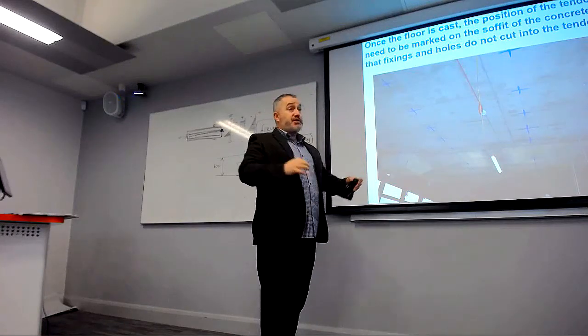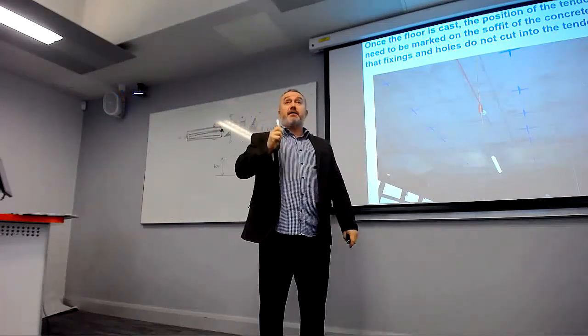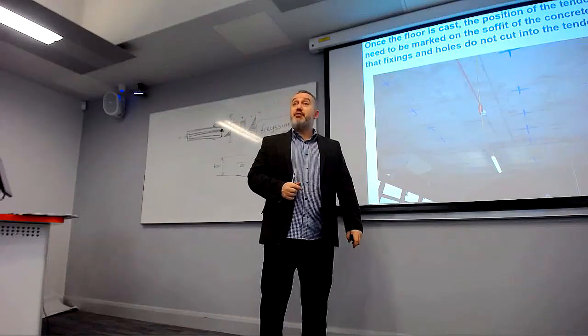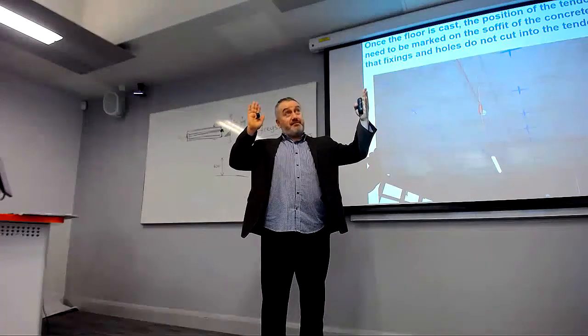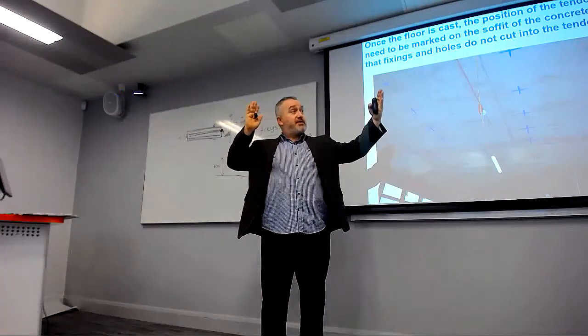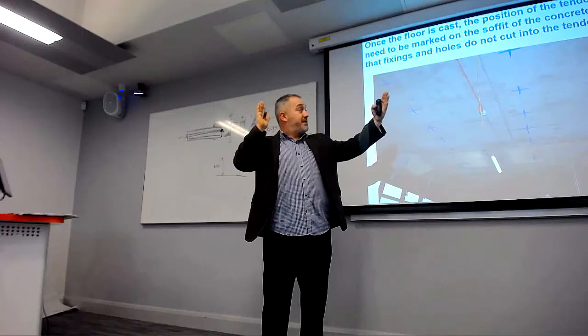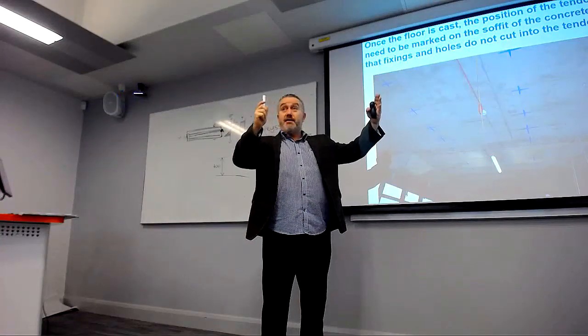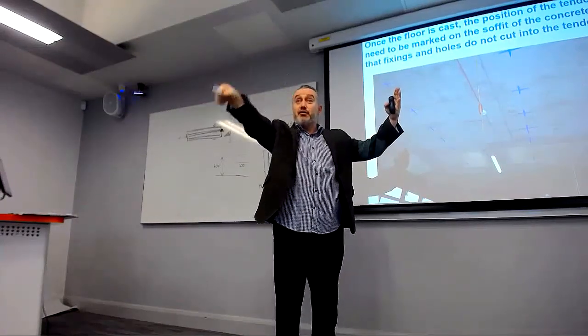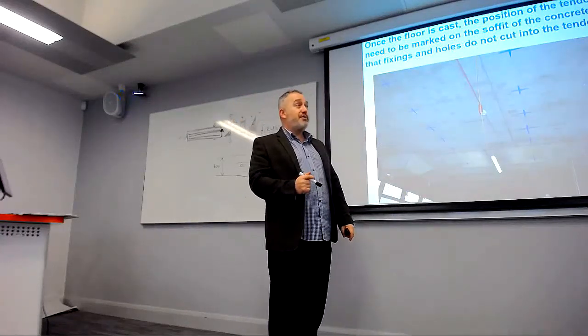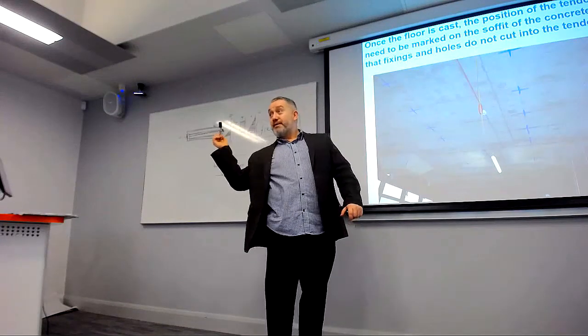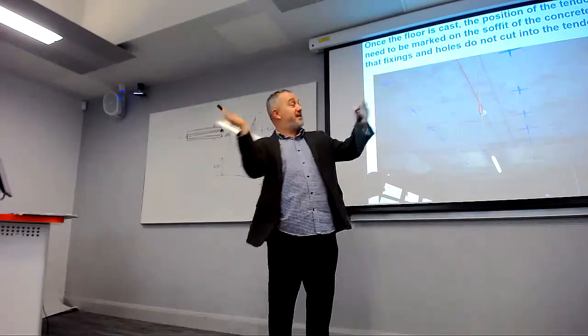Because it's under tension, if you search for demolition of a pre-tensioned building, because the steel's in tension and the concrete is under compression, if a demolition excavator cut through the concrete, the steel would just snap and fire the concrete about.